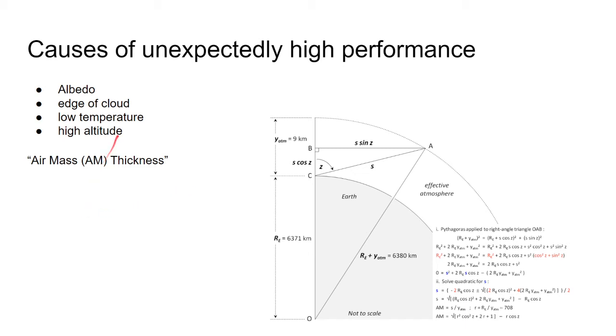High altitude is another one to be careful for when you're using your sizing calculations. Even the PV Watts weather station selection, if you're up in a mountainous region, you want to make sure your data set is coming from a high point of elevation, because the Earth's atmosphere does play an impact.